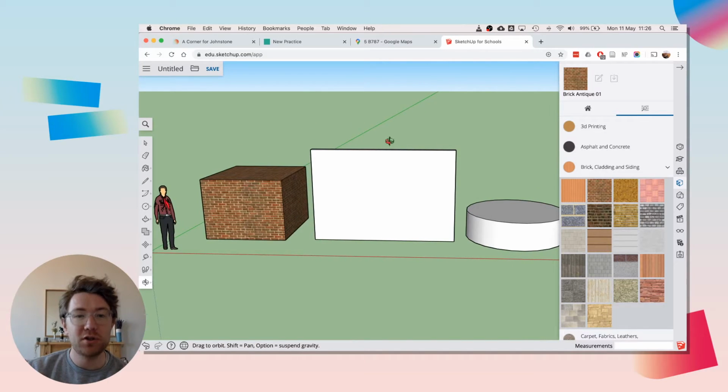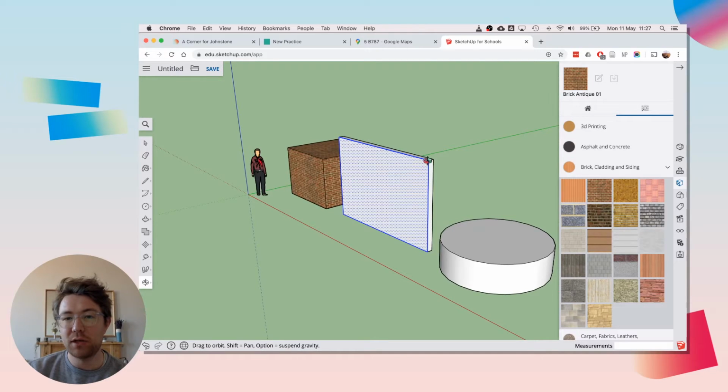There's other ways of doing it. If you've got lots and lots of shapes, say shapes that are behind here, and you don't want to drag and select lots of different shapes, you can click on this shape and you'll select one item. But if you double click, you can see it selects all of the edges around the face that you've tried to select. And if you click 3 times, so you treble click, it'll select everything. So it'll select the whole shape that face is connected to.